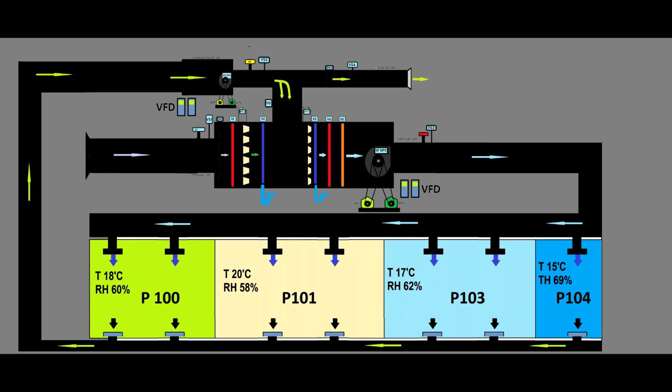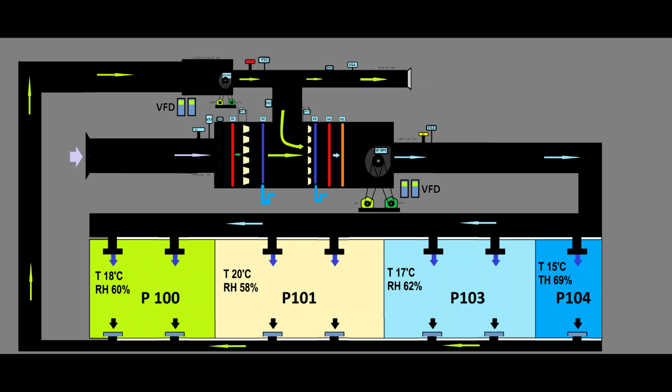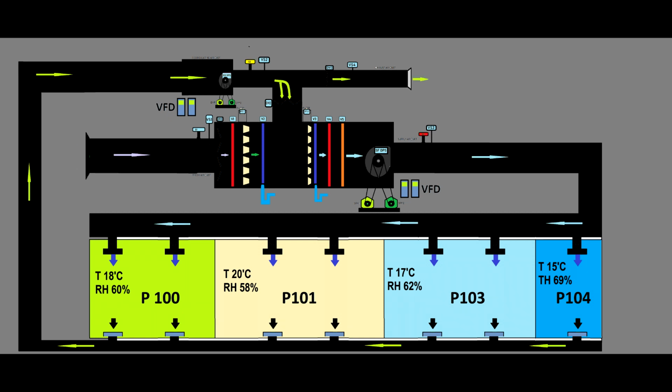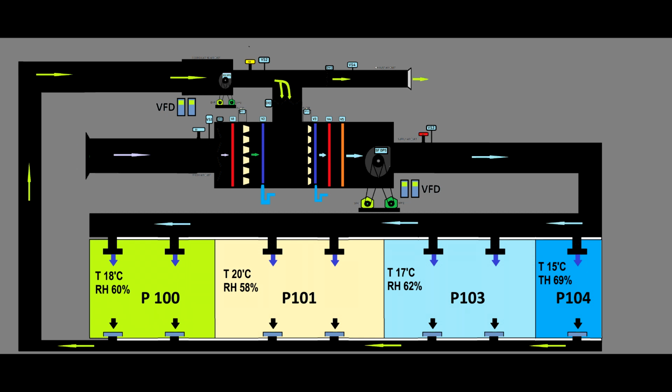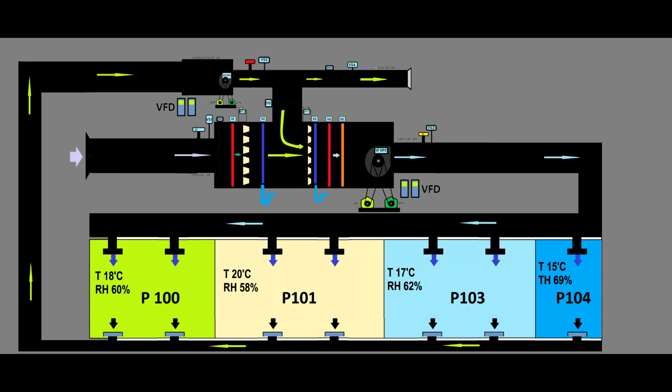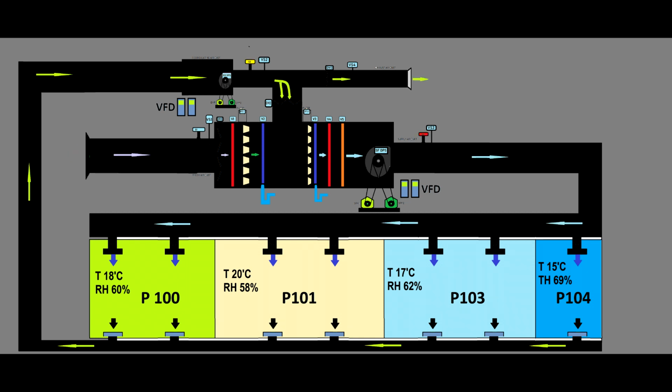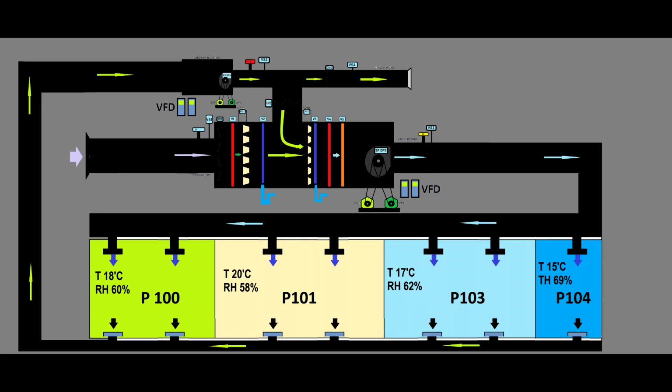One is the supply air on the right hand side, and the one on the left hand side is the return air. The return air will read the temperature of the entire return air. It will read the temperature of all 4 rooms at the same time, a kind of average, and you wouldn't know which room needs more or less, and you will adjust the airflow temperature as per that average reading.